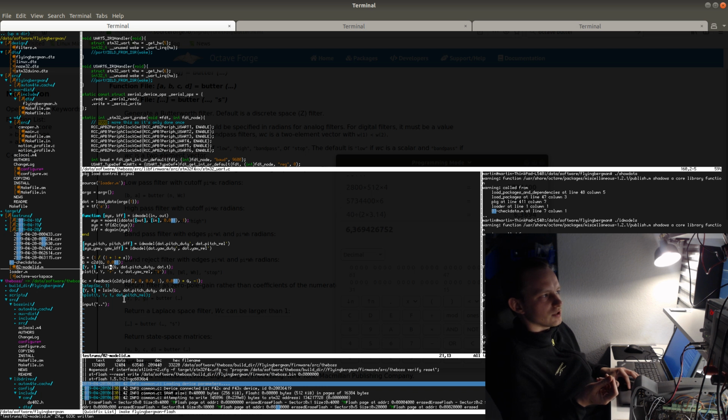But because the DC line voltage, for the most part, doesn't rise above the DC voltage level if we're operating within limits, we can just use the duty cycle. So this is how to do the quick approximation without any model identification, by repeatedly plotting this function.